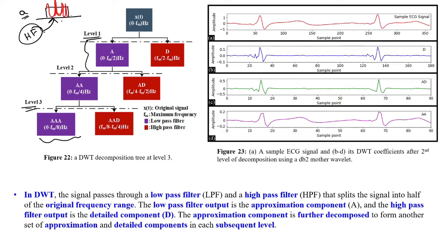In the Fourier transform, what was our knowledge? When we try to do the Fourier transform, we should take the transform of at least one time period of the signal. If we take less than that, we will not be able to analyze the signal. The same thing happens over here also. When your scale is smaller, a low frequency component will not come within that small scale. However, higher frequency components will fit into the smaller scale of these wavelets, so we will be able to analyze the high frequency components.